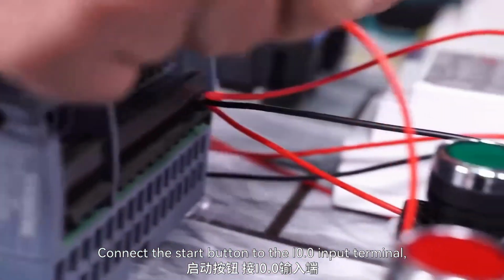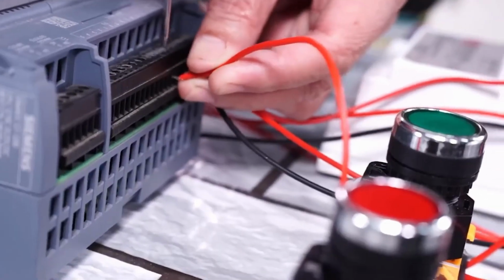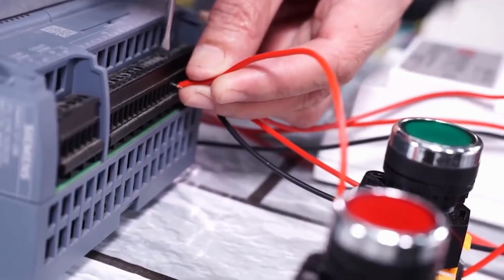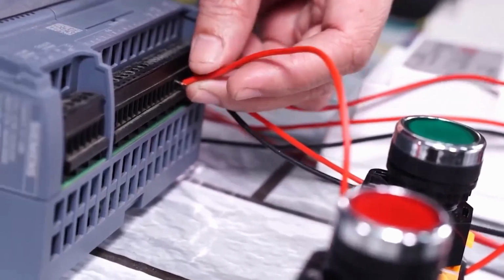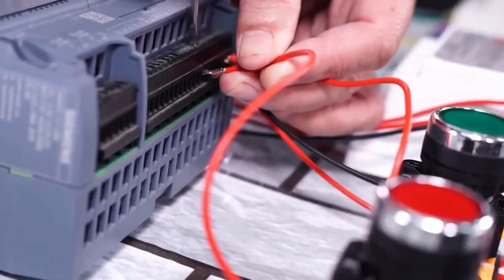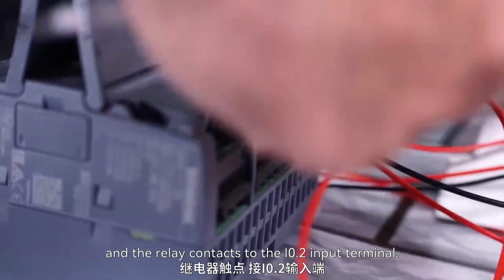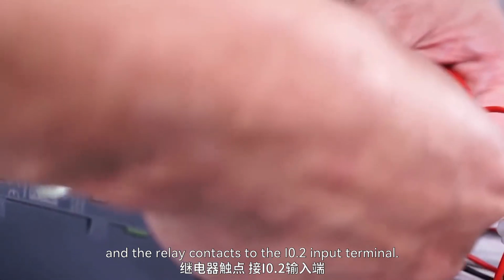Connect the start button to the I0.0 input terminal, the stop button to the I0.1 input terminal, and the relay contacts to the I0.2 input terminal.